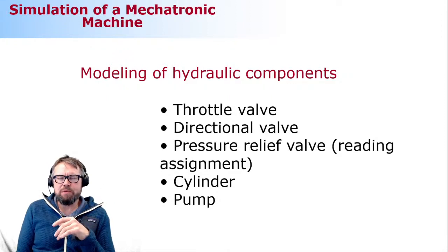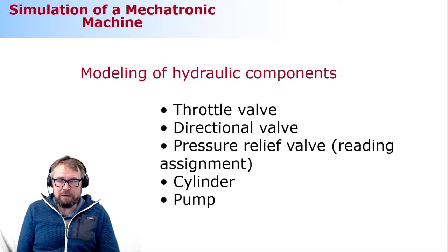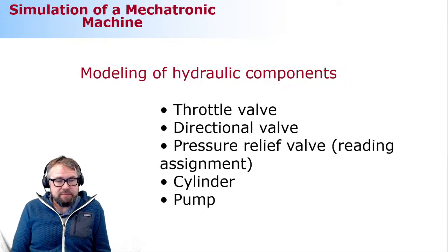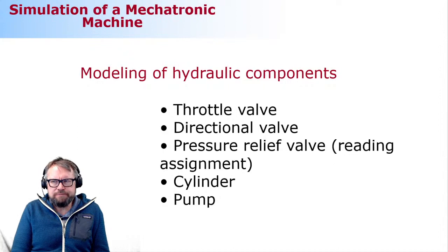How can you possibly save a little bit of energy by having a bit more advanced pumps? Because the pump is the one that is producing the energy to the system. And then you're kind of losing it in the system, and that's how it works. And if you keep on producing energy to the system regardless of the need for energy, then your efficiency is not going to be very high. And this is exactly the problem in conventional hydraulics. A little bit of a problem in modern hydraulics as well.